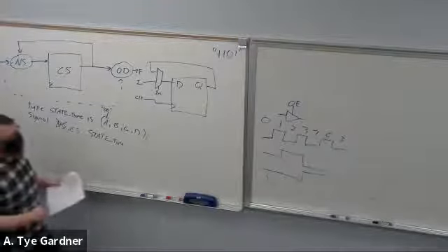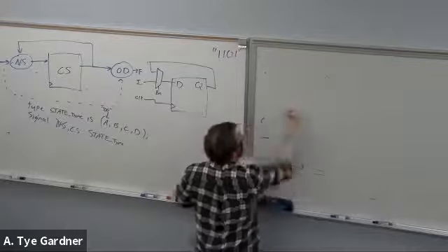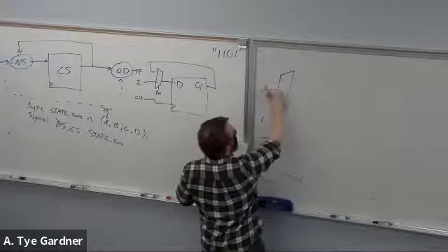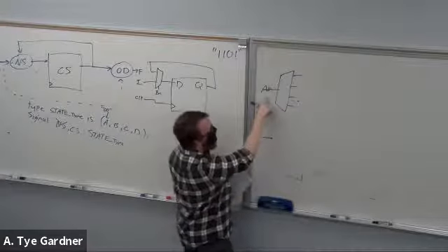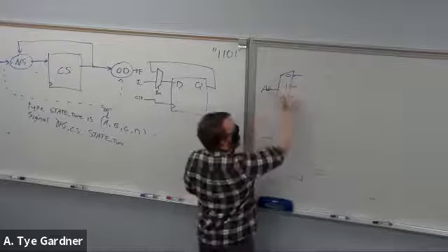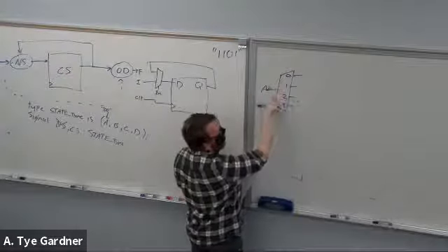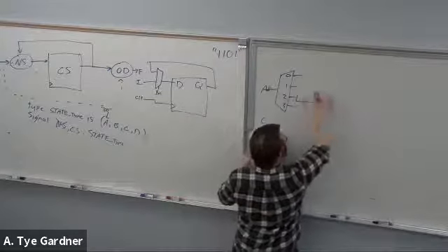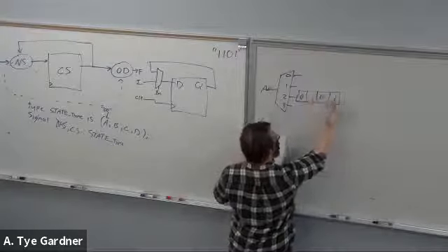So number 12 was just a really simplified address drawing. And it was just testing to make sure you remembered what an address decoder did, right? So, well, I was testing 2 things. The address decoder, when I give it an address, 0, 1, 2, 3, I have to send an activation signal to one of these and only one of those. So they were horizontal. So this row was the one that had what I was looking for, which was 0, 1, 0, 1.